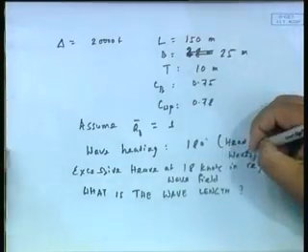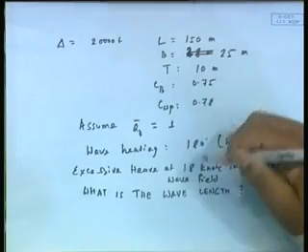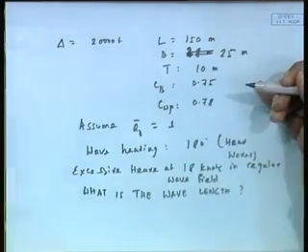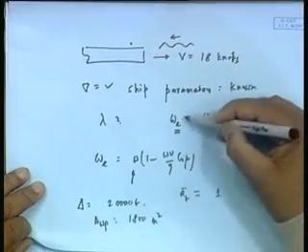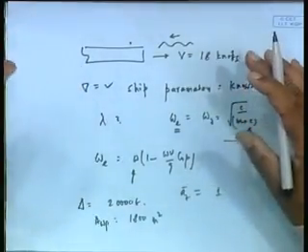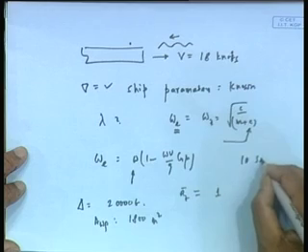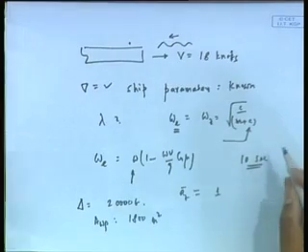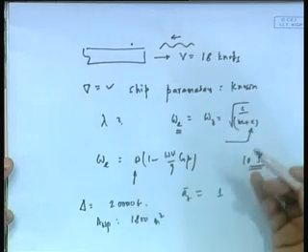Please remember that this is a forward speed problem. So, the omega you find out is omega e. Omega e is the natural frequency. Omega e is not omega. Some people make this mistake: they find out the natural period, say something like 10 seconds, and think 10 seconds is omega and find out the wavelength. That is wrong because this is omega e. From omega e I have to first find out omega and then find out the wavelength for that omega.